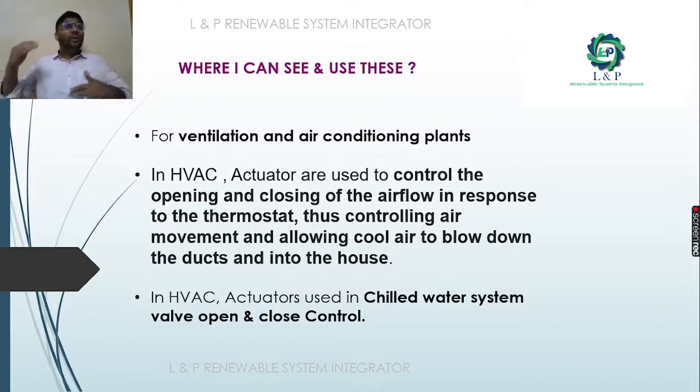What is the advantage of these controllers? If you go for a PLC, the programming will be different and the cost will be a little high, and if you go for a DDC it will be less compared to PLCs. But when you go for these VAV controllers, they are application specific. Everything is pre-programmed. You just plug and play, and configure the basic settings so that you can operate your plant successfully with the help of these terminal box controllers for specific applications.